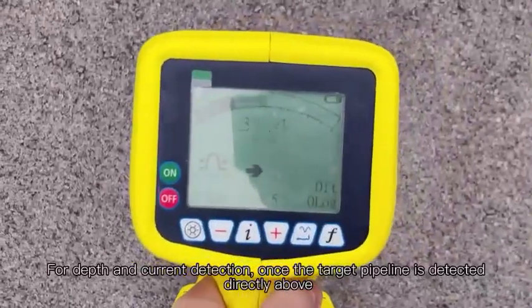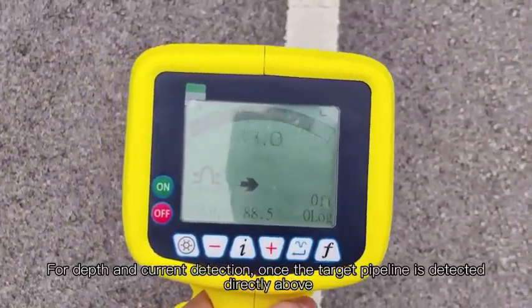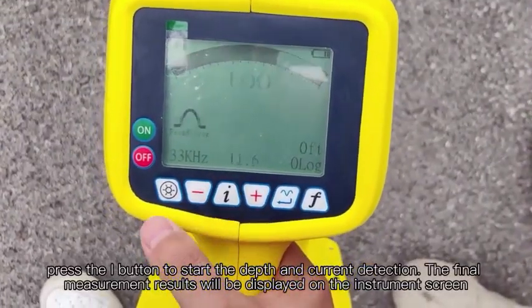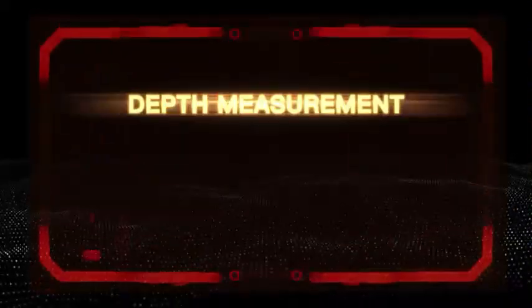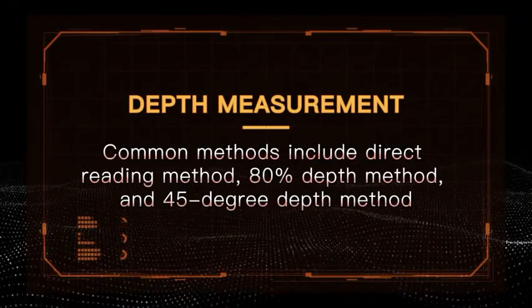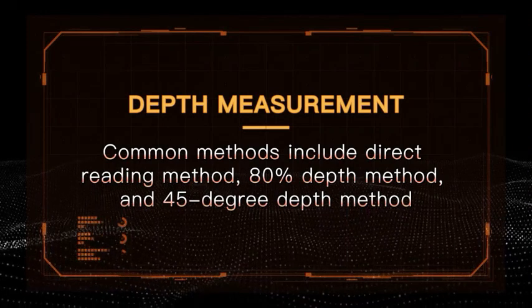For depth and current detection, once the target pipeline is detected directly above, press the I button to start the depth and current detection. The final measurement results will be displayed on the instrument screen. Depth measurement. Common methods include direct reading method, 80% depth method, and 45-degree depth method.